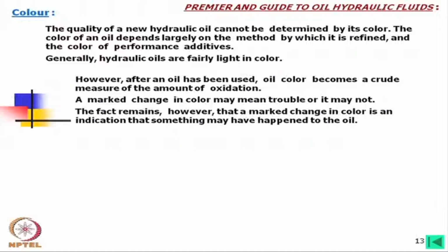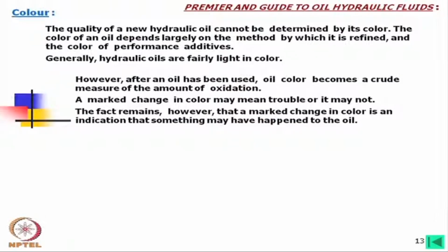Among the hydraulic components, in any hydraulic system, the first thing that has to be changed periodically is perhaps the oil, and that period is shorter than for any other component. Next might be the seal, which you also have to change. So in that way we have to continuously inspect the oil condition. This is the health of the oil, or the specification of the oil, and we should check it from time to time.